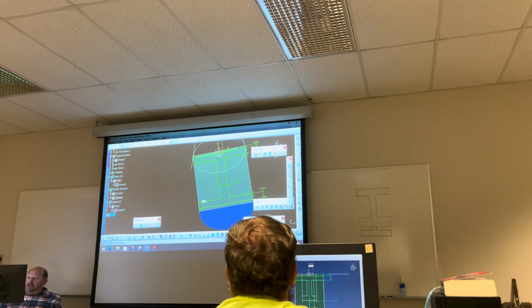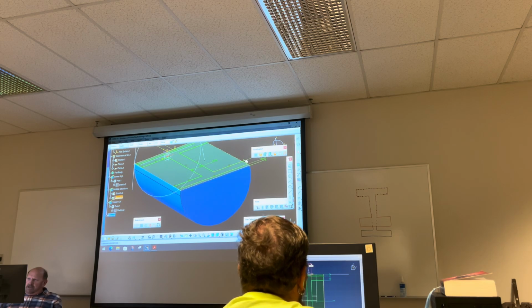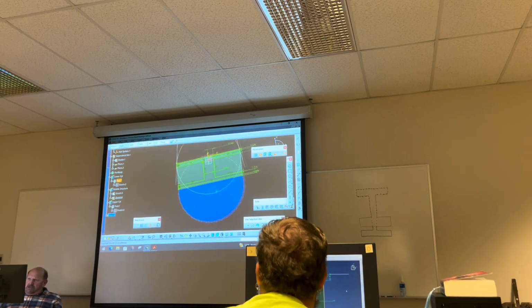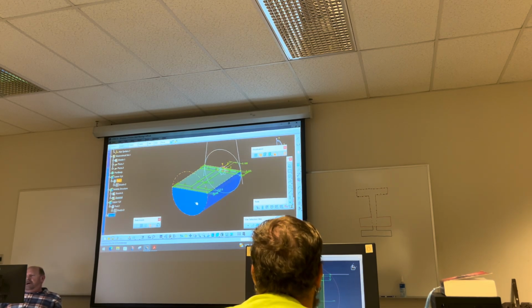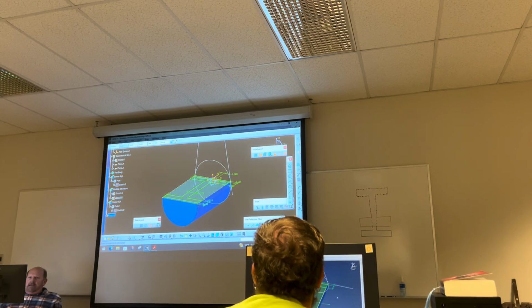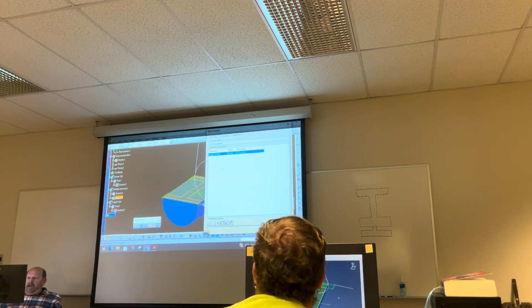That one should be in position. Hopefully, looks like I'm coincident all the way around. Got a coincident marker there. So I should be good. The real test is gonna be when I build it, and I go to unite it to the top and bottom, how it looks. So it's fully constrained. If I go in and I look at the sketch, I got one profile that's closed.